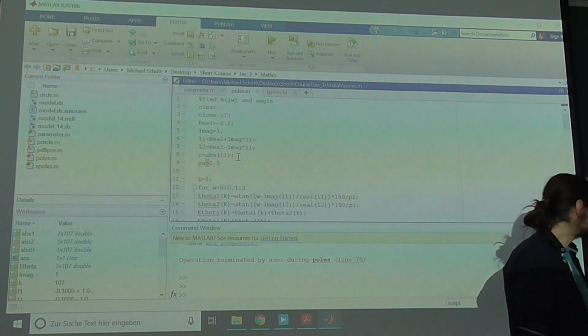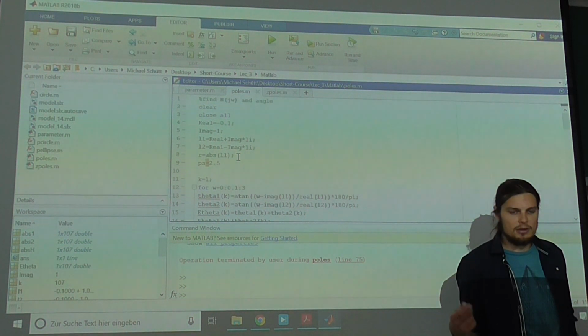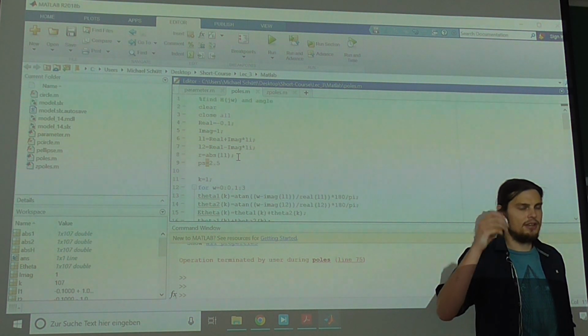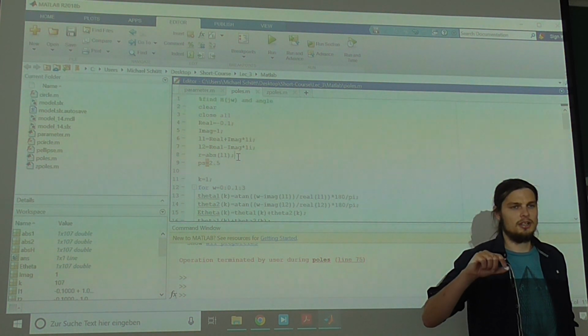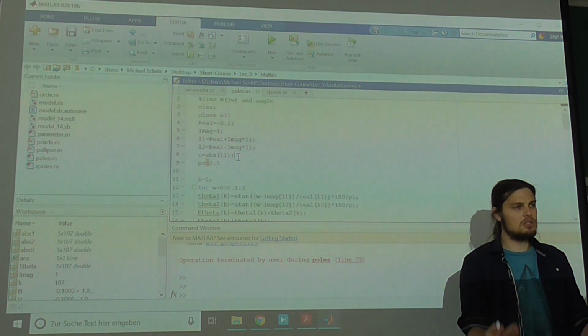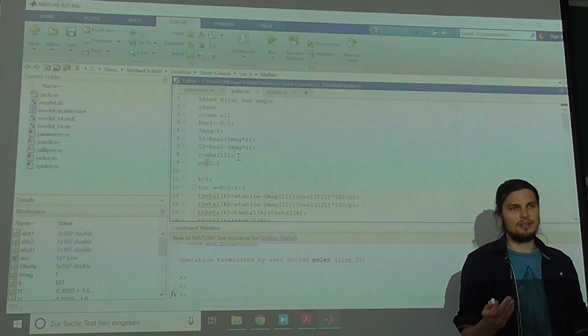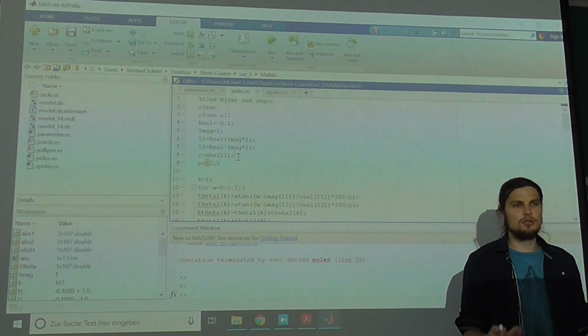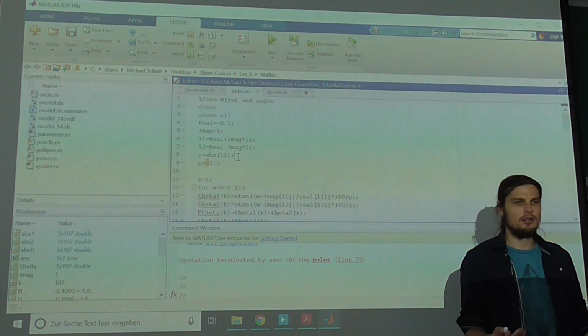And you will see this if you use a Luenberger observer and you have low bandwidth, you will see that the dynamic stiffness drops a little bit. So it's basically weighing between dynamic stiffness and filtering properties. That's what you do with the observer bandwidth.